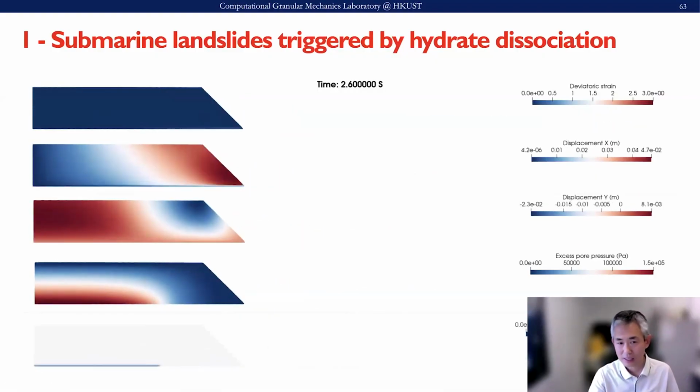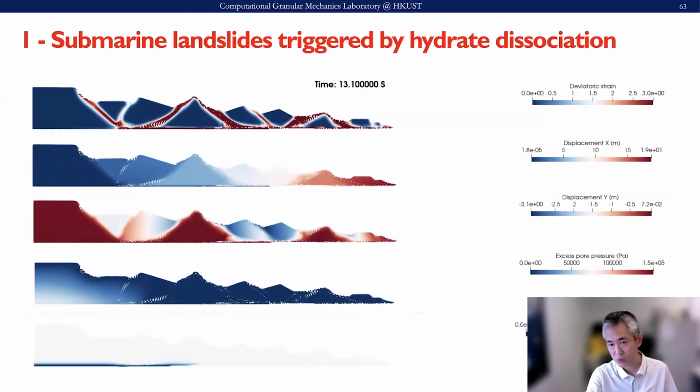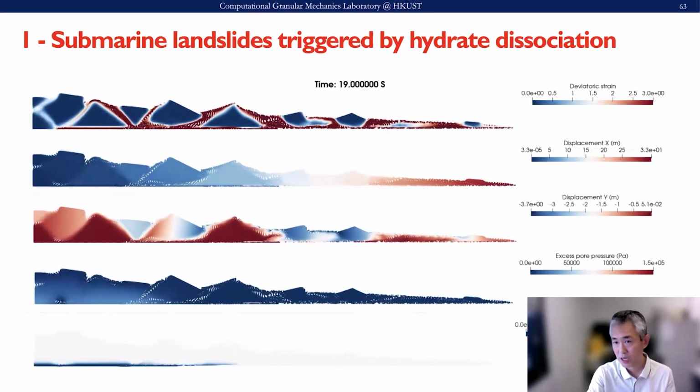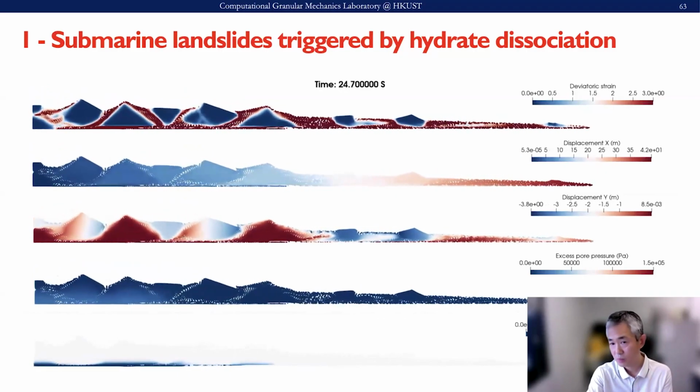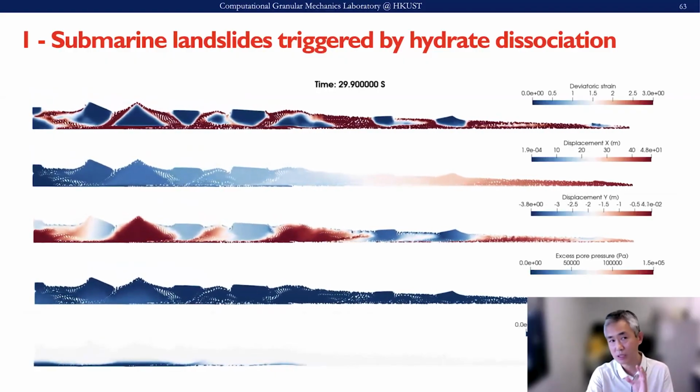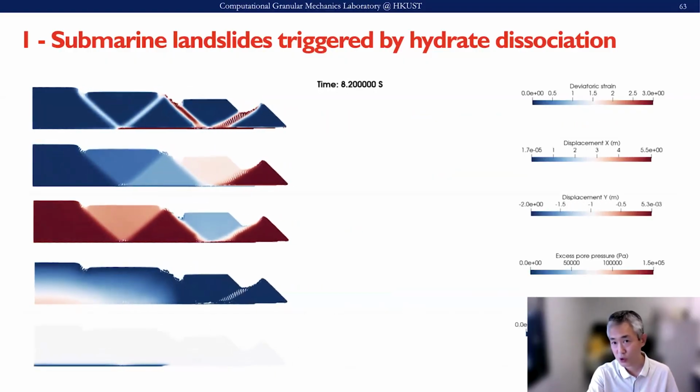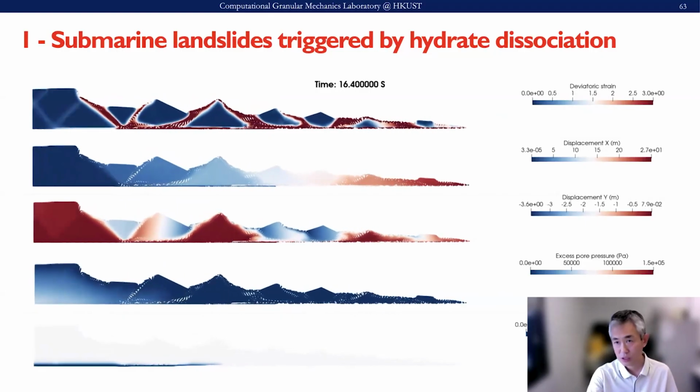So this is one example showing that we can use this thermo-hydro-mechanical coupling framework and multi-scale approach to simulate a submarine landslide triggered by hydrate dissociation.